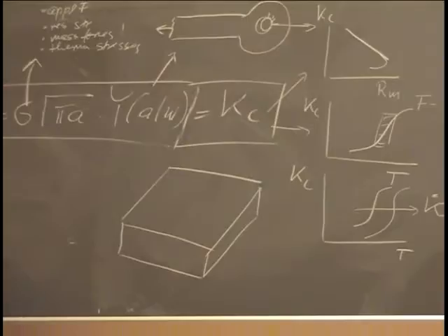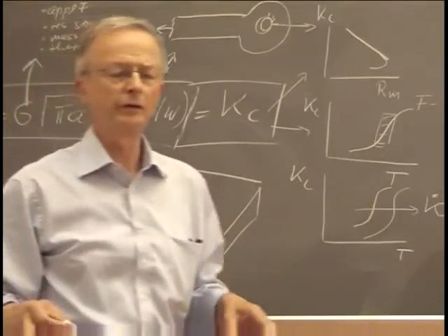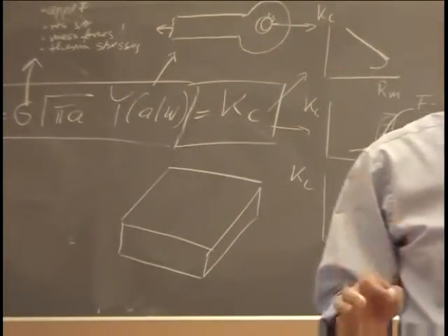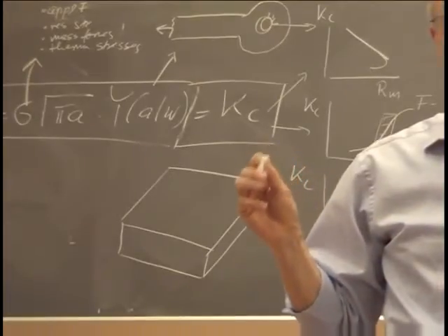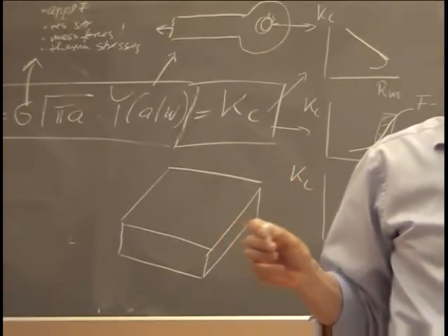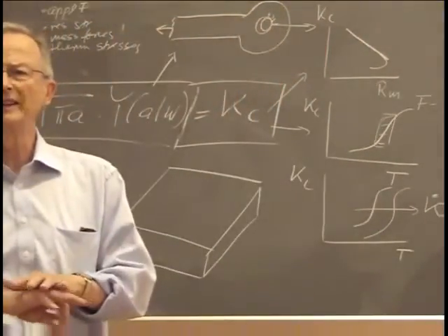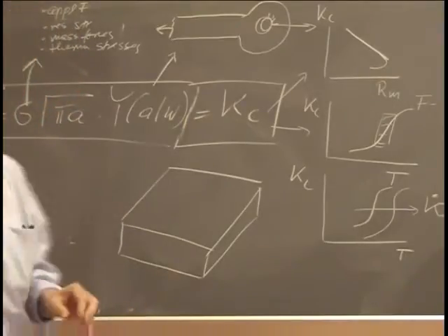And you have at least 6 different orientations, and in these different orientations, we have done all this in detail. You have substantially, sometimes substantially different toughness values. It is due to the microstructure, due to the rolling process, the microstructure is aligned in the rolling plane and in the rolling direction.